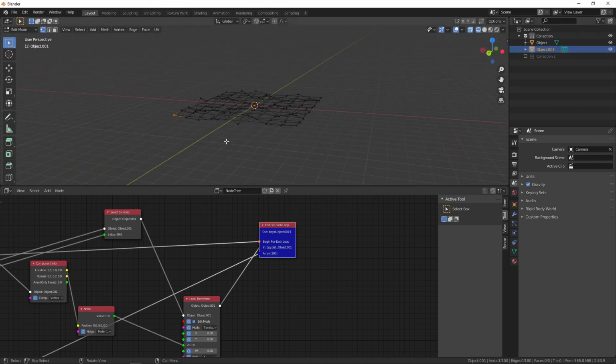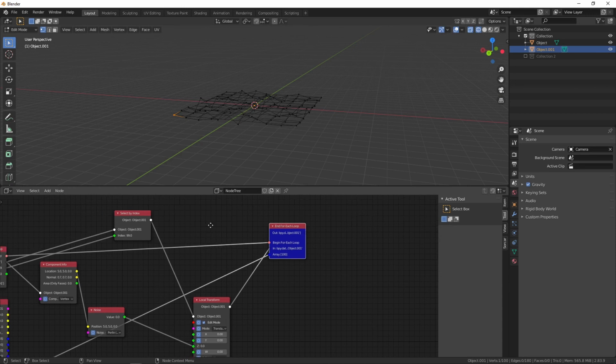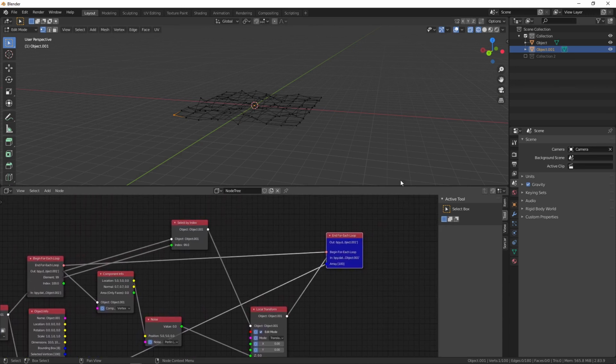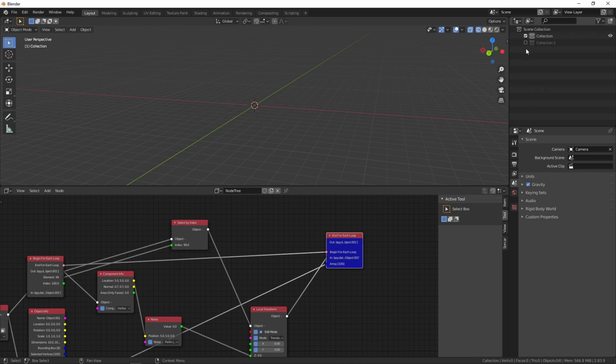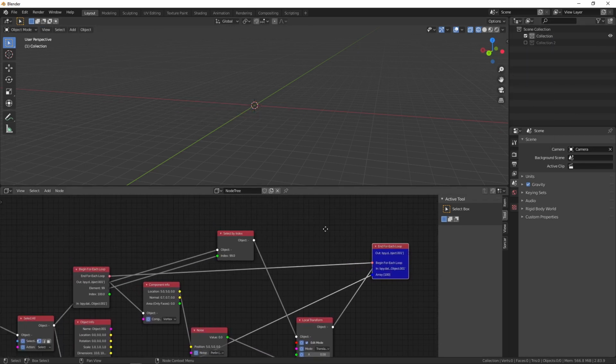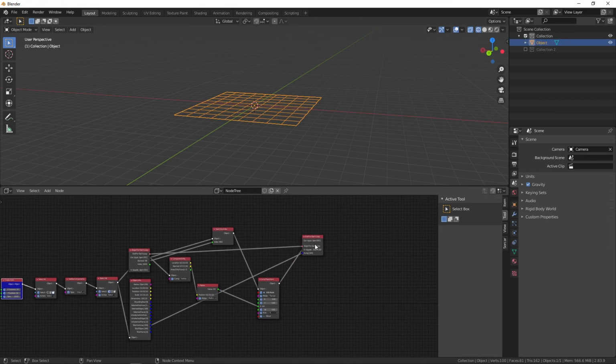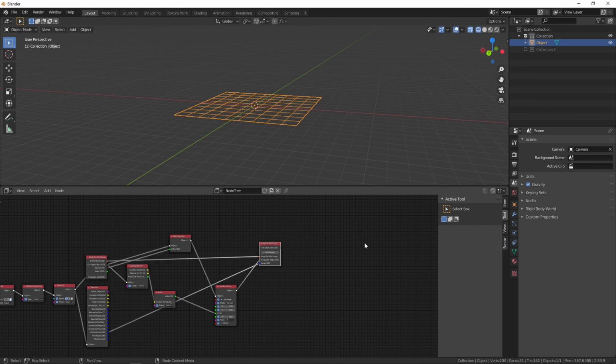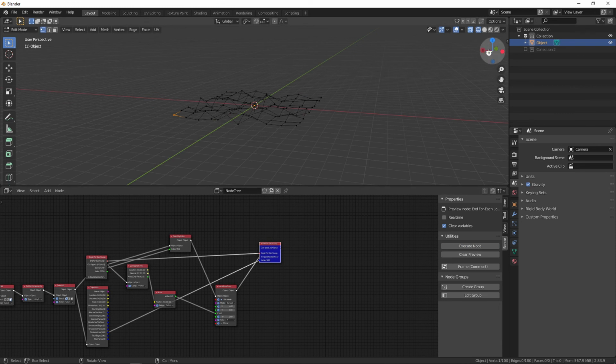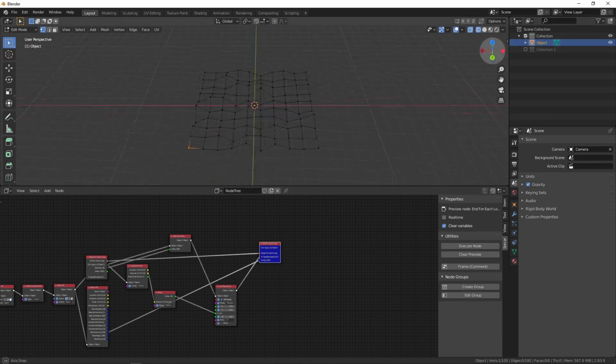Now, you see two meshes on there. I've made a change and sort of broken how it's generating procedurally. I'm surprised this hasn't come out before this, but it's very simple to fix. You just delete everything, which seems bad. You can either reset your previews, or you could go to the end node here if it was already selected and hit execute node there, and that regenerates everything.